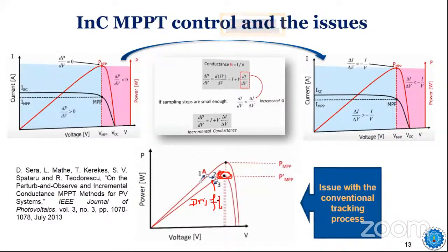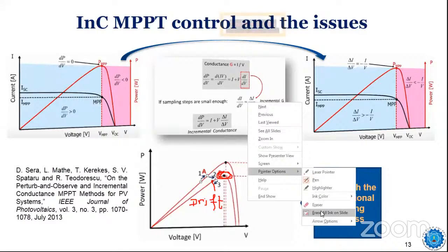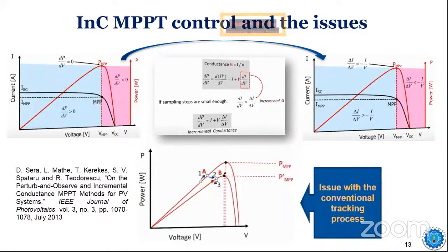Drift is moving towards the wrong direction, wrong movement. Our MPP is on the right hand side, but our algorithm is trying to track to the left hand side. After some movement, it will see again that, no, I have to go to the right hand side, and then it will come right after one or two movements. But this has moved in the wrong direction, right?